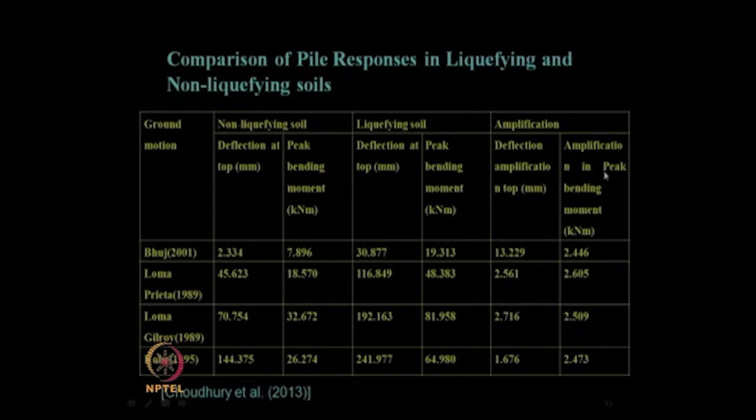This amplification of displacement as well as of peak bending moment can occur when your soil condition just changes from non-liquefiable to liquefiable under the same input earthquake motion. These details are available in the publication by Chaudhary et al., 2013. This is a keynote paper at the Bandung, Indonesia conference, PILE 2013.